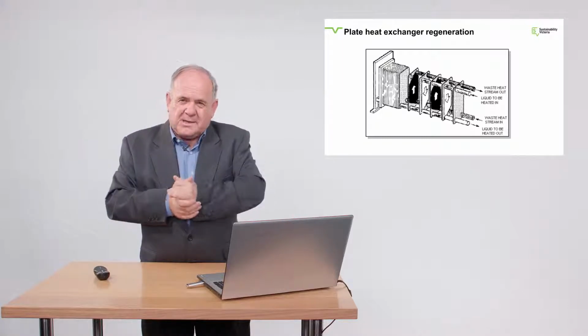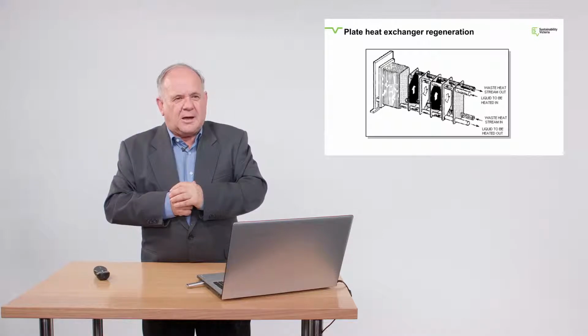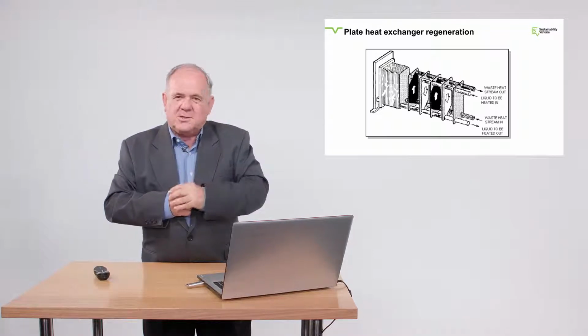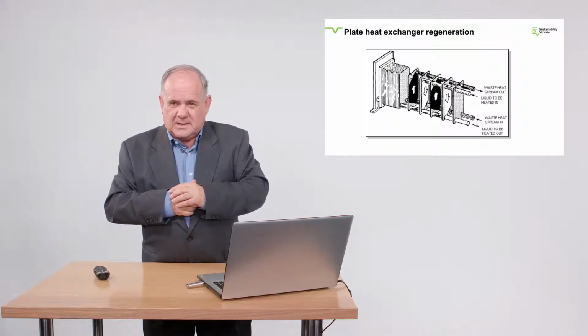The impact of that is new heat exchangers of that type are 90% regeneration. So in other words, they're only using 10% of the heat and cooling that you would use if you had to heat and cool without a regeneration section.